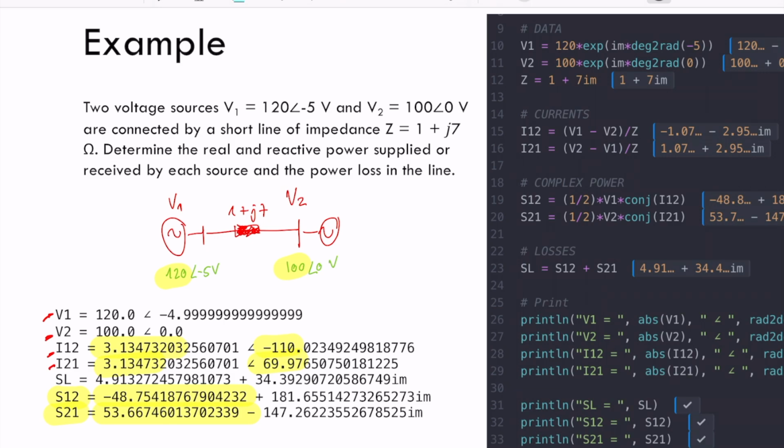And the key, and this is important, is not only in the value of the magnitude, but also in the phase angle. So it depends on what those phase angles are, and it actually gives you insight into the direction in which the energy is sent, from 2, right? And typically it goes from larger phase angles to lower phase angles.